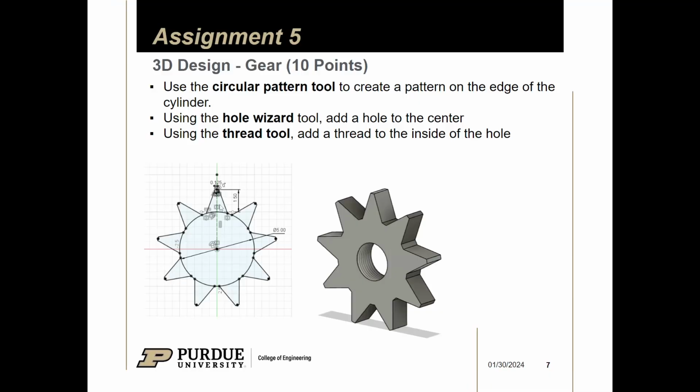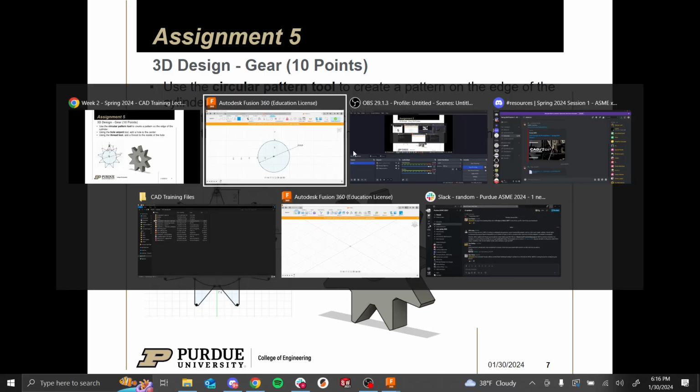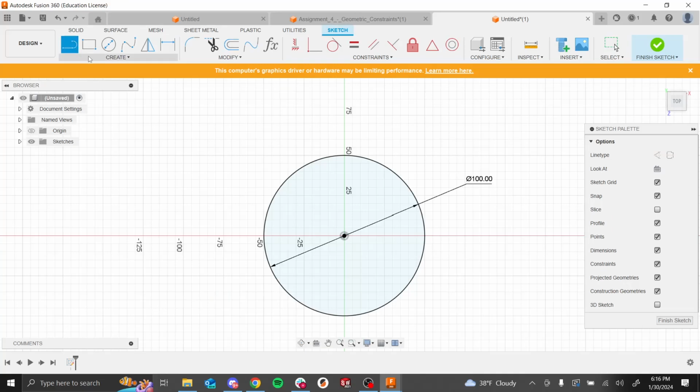All right, so now I'm going to sketch the tooth profile, right? I'm going to create half of a tooth, and we're going to copy it multiple times to create the whole gear, right? So over here, I'm going to start by making a line vertically from the center. I'm going to go out horizontally and then down like that.